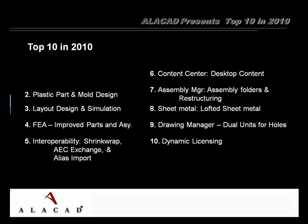Mold design, you could always do mold design, but they've added specific content center data for injection mold design. Die sets, bearings, typical things that you would use in the injection mold design, they've got a content center specifically for that. On top of all that, they've given me the tools to do mold flow analysis within the software. So now I can not only create my part quickly, generate my mold, and evaluate my mold before I ever create the first part, thus improving my digital prototyping.